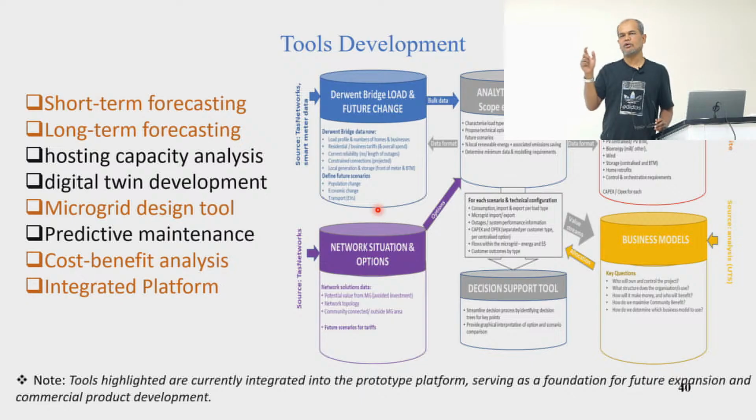Once you have a very good idea about this pattern, then you can think of, if I have a microgrid, what should the capacity be now? What should be the capacity after 2 years, or after 10 years? So you can plan accordingly, because we don't want to install now what will be required after 30 years, right?